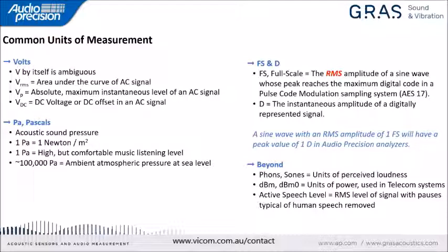Pascals are the preferred representation of signal amplitude when that signal is traveling in air. Volts is when we're representing an audio signal in the analog domain, an electrical signal. But as soon as we put that signal into a speaker, and that speaker turns that into sound pressure, we would represent that sound pressure in pascals.